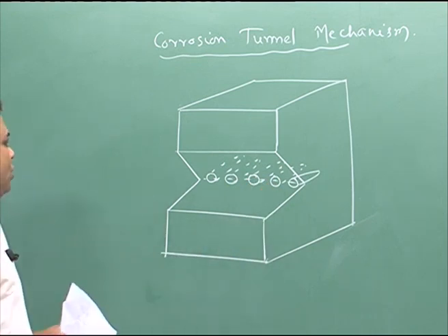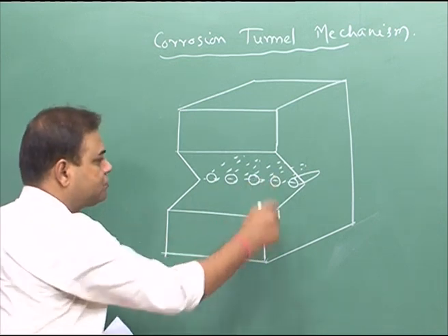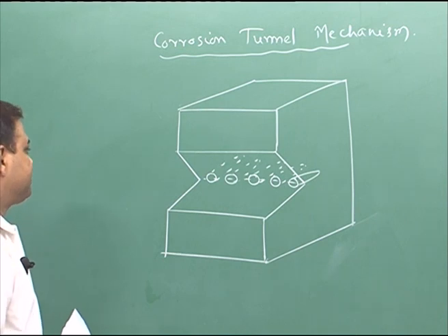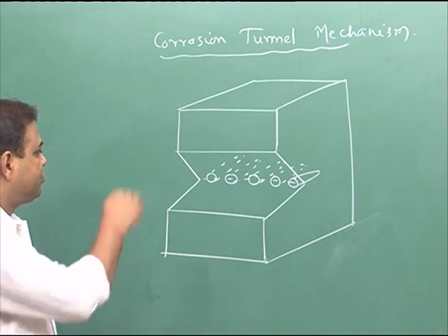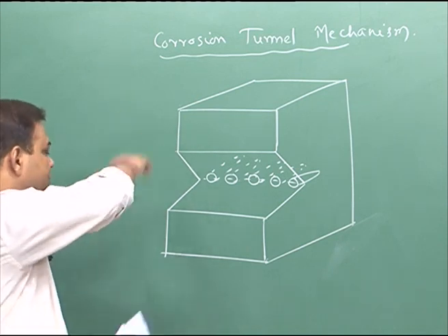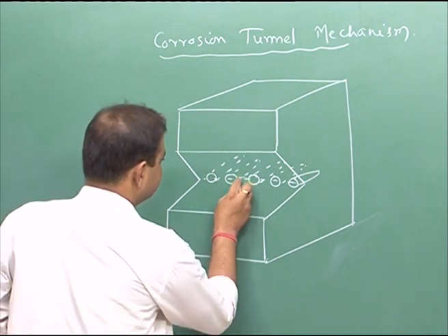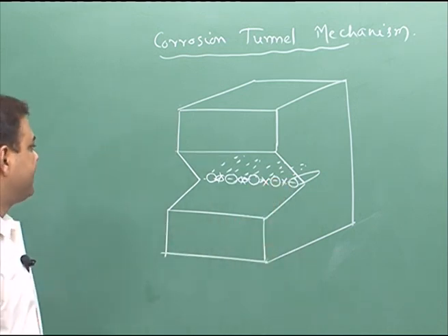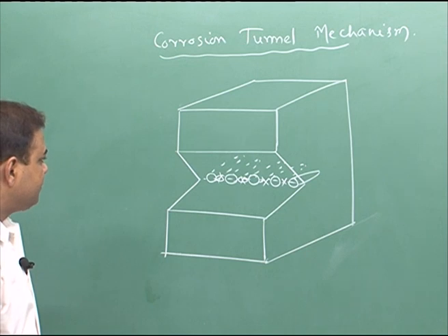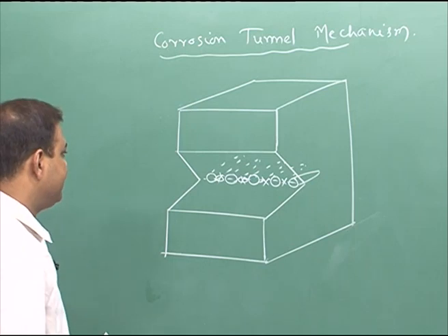There the entire load will be experienced, and due to the small cross sections of those ligaments, the stress becomes very high, and then it goes beyond the fracture stress, the UTS, and then the material fails by mechanical failure mode. And so, in these small unbroken ligaments, you might experience ductile failure, because the stress goes beyond UTS and then the material fails as per the mechanical failure route.